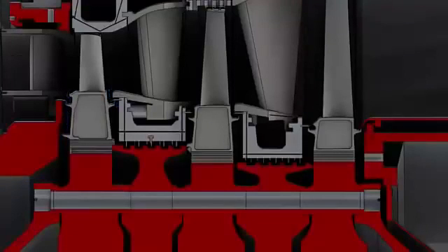The first stage aft wheel space is cooled by the compressor discharge air supplied through the second stage nozzle. The second stage forward wheel space is cooled by a portion of the first stage aft wheel space cooling air, which passes through the labyrinth and brush seal. The second stage aft wheel space is cooled by the rotor internal cooling air, which passes through the slots on the forward face of the second wheel spacer. The third stage forward wheel space is cooled by a portion of the second stage aft wheel space cooling air, which passes through the labyrinth seal. The third stage aft wheel space obtains the cooling air from the exhaust frame cooling system.